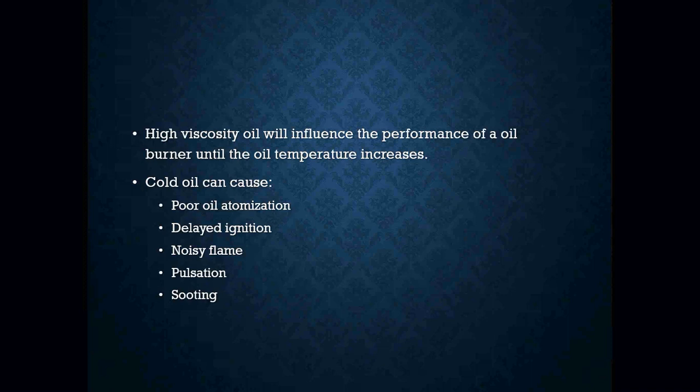It can cause poor atomization of the oil through the nozzle. It could clog up a nozzle. It could cause delayed ignition. It can cause a noisy flame. It can make the boiler or furnace sound like it's rumbling off the floor. It's going to cause pulsation. You might hear the burner run, but it sounds like it's pulsating. It can also cause a lot of sooting on an oil burner.